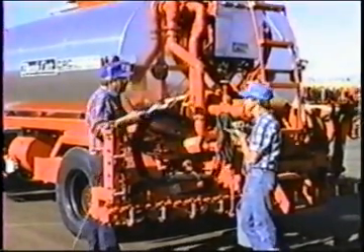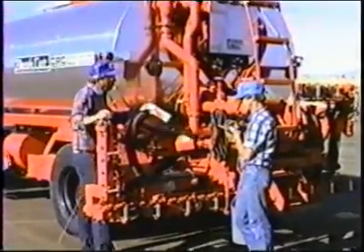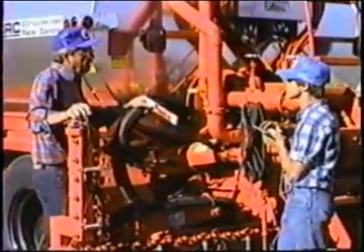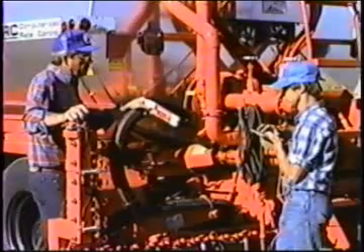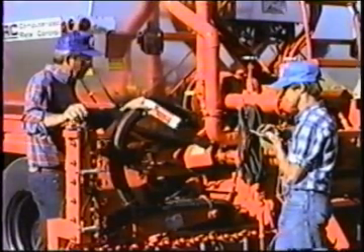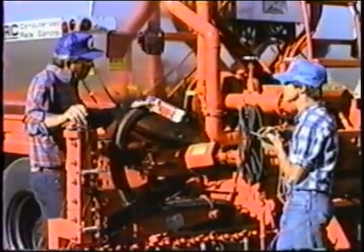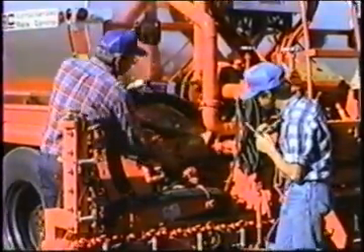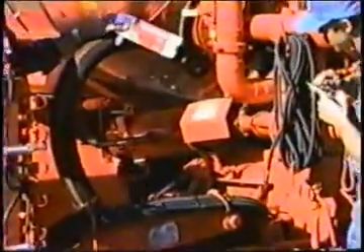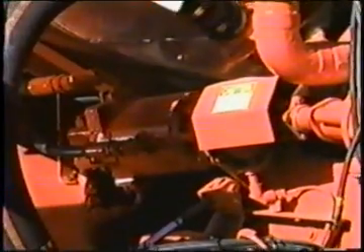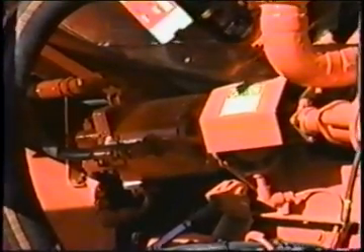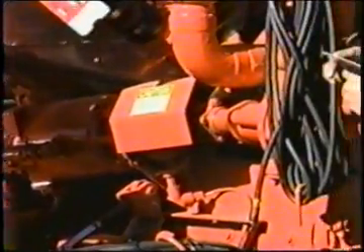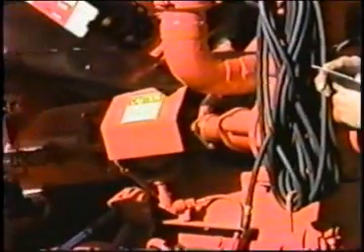So what that's telling us, if we set the pump at a particular speed, at the travel speed, it creates a spread rate that we're after. This pump is driven by a hydrostatic transmission. This is the business end of that. From the cab of the truck, we can regulate the speed of that hydraulic motor that drives the asphalt pump.